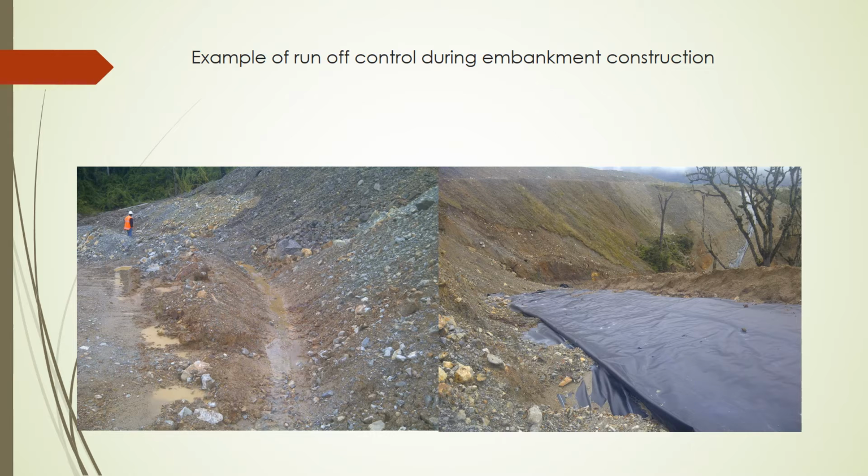Water control is not something just done once off. It has to be done at the start and right the way through the project. Here we see erosion control happening whilst we're constructing. On the picture left, we see a simple drain to a collection point where a sump is constructed to drop out sediment before it's evacuated into the environment.